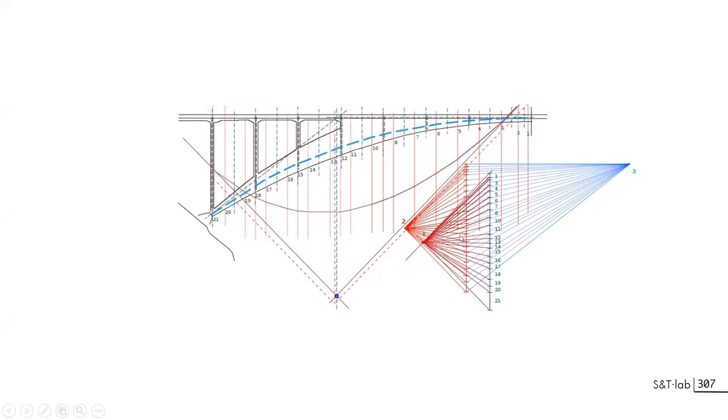I won't enter into detail, but what you can see is that this direction here, this direction here and this direction here give you the pole that enables you to start with the rays that will let you draw the first line into the arch. And this first line can be compared in position with the position of the center of gravity. Where these points are not the same, we have a small lever arm that will give you directly the bending forces along the arch.